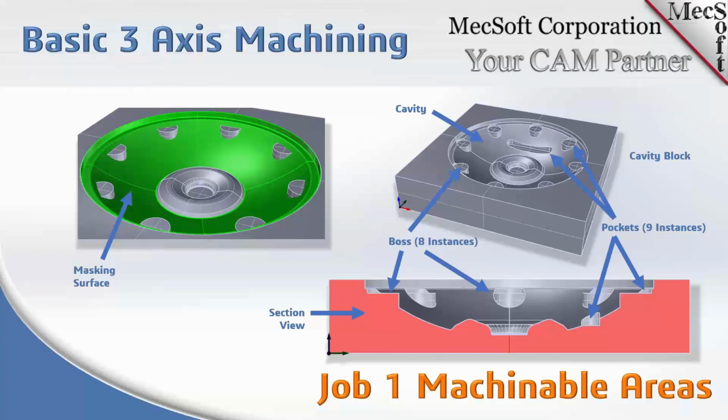Yes, if you're familiar with our products, if a surface is visible and you're running a 3-axis operation, it will enter into the calculation of the tool path. So if you don't want something to be machined, you want to mask it or turn it off. Some people just have different layers that they have on and off depending on which operation they're working on. Okay, so let's go to the next slide.